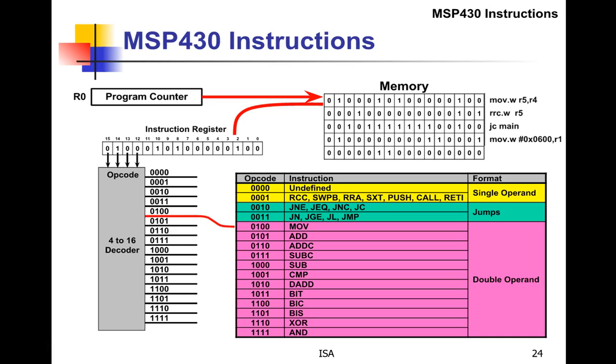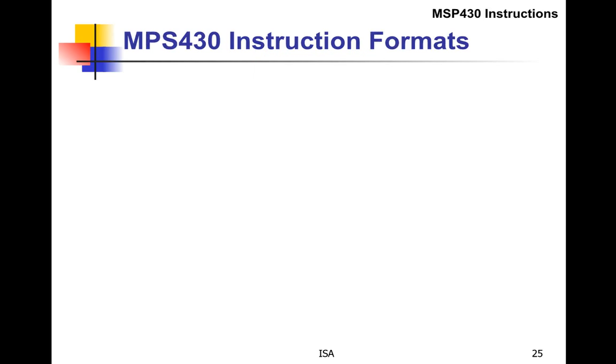And over here, if you look up on the right-hand side, this instruction really says move R5 to R4. And if you look at the 4 bits, that's the move instruction, then this is a 5. Then there were 4 bits that we don't care about, but here is 4. So we're moving R5 to R4. And so it takes 1 cycle to fetch the instruction.